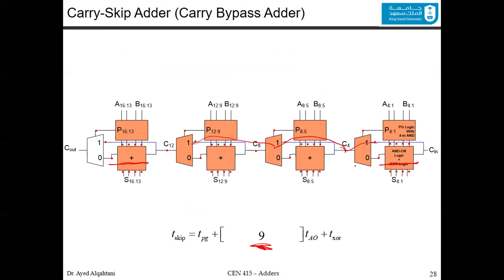This is what we did. So what happens since we ripple? That's 3, because it's 4 minus 1. Here is also 4 minus 1. And we skipped through 3 multiplexers: 1, 2, and 3. The last one didn't do anything to it because we are rippling. And that's why we have k minus 1.